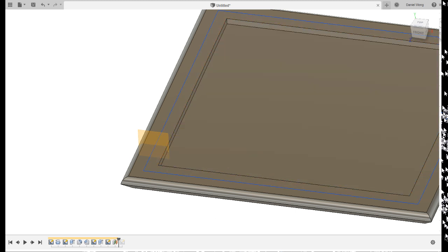And now back in the timeline, I can go back forward in time and see that the circle is there. Can you guys see that? And now, because that sketch has already been made, I can redefine the sketch plane, and instead of drawing it on the original front plane, I can move it to this shifted plane here, and I can press OK. Okay? Everyone get that? Great. So, now that we have that, hopefully we should be able to do our sweep.